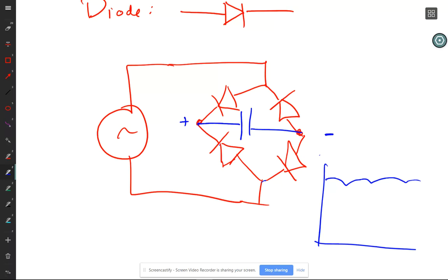We often then will take what we call a voltage regulator. We can do that with a Zener diode or something like that, that will cut it off and just make it so it's constant without ripple somewhere below that ripple level.